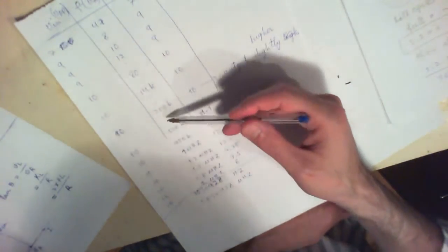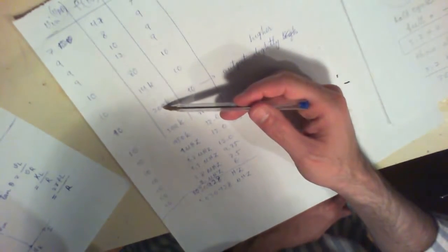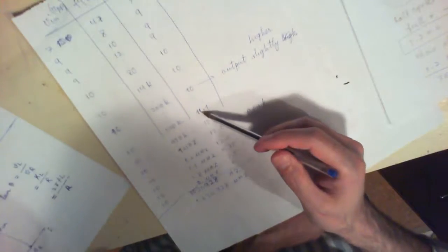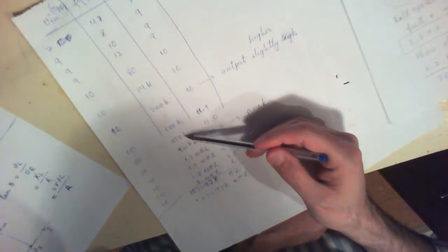And over here the output was slightly higher than the input, and this is something that has something to do with the inductor. Okay, and then you go all the way up to 500 kilohertz. The input is 10 volts, the output is about 11 volts. 950 kilohertz, 10-12 volts. 1 megahertz, 10-12 volts. And that was the peak of that.